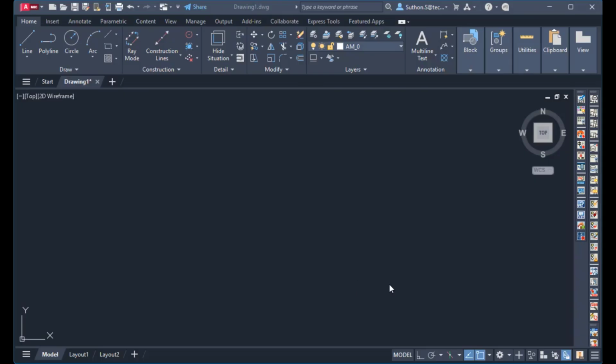For the attribute made in full AutoCAD, can it be imported or used in LT with all the parameters set up, meaning it works in LT even if we set it up in the full version? I think it doesn't work that way, because AutoCAD LT has a limitation: the block in it is static, right? Yes, if you create the static one in full AutoCAD, maybe the attribute is going to convey. But if you create the dynamic block, LT can't support that. So the parameter should not go, or it will have an error, because LT is quite lower than full AutoCAD. So we urge you to use full AutoCAD instead.